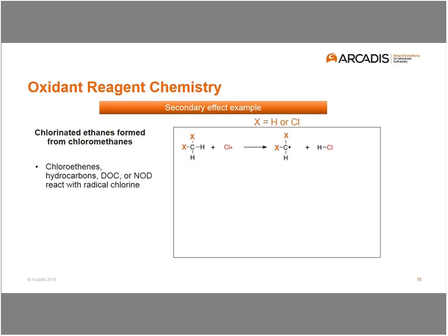So the first reaction to look at is these chloroethanes, hydrocarbons, natural organic matter, or whatever, they can interact with radicals that we create as a result of injecting our pretty dramatic chemistry. So chloride is one such geochemical parameter that's present universally. It's going to be present at tens to hundreds of milligrams per liter in normal aquifers, thousands of milligrams per liter in saltwater, tidally influenced aquifers.